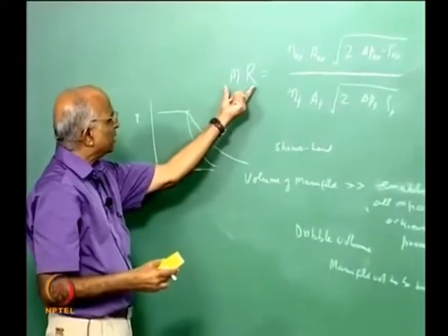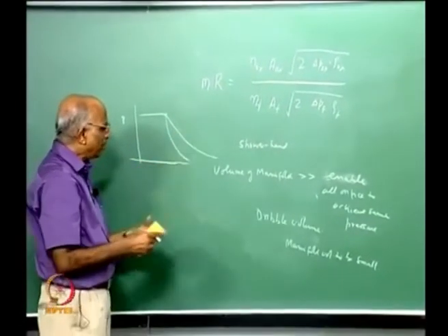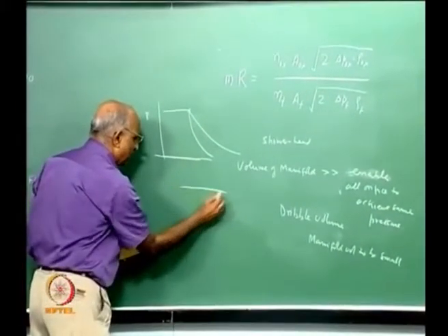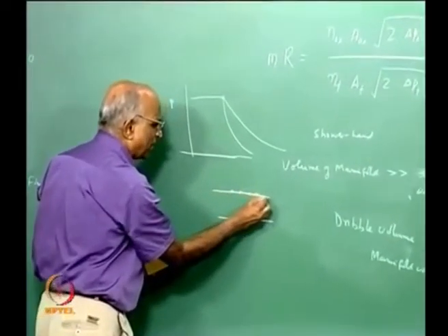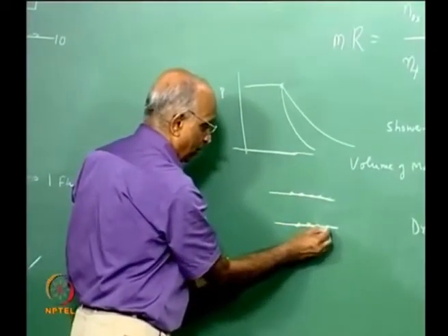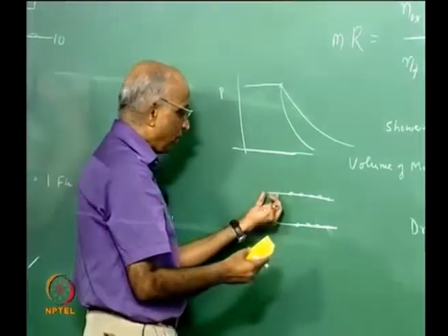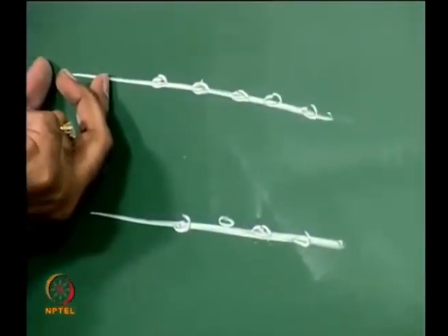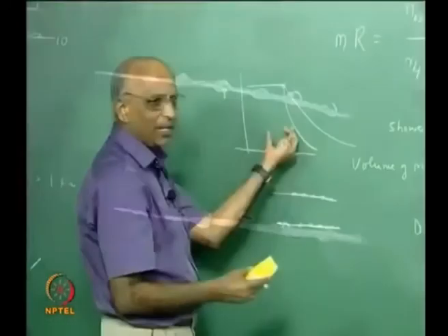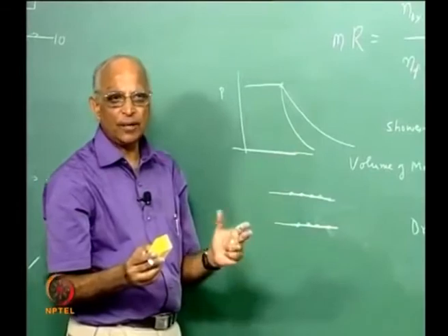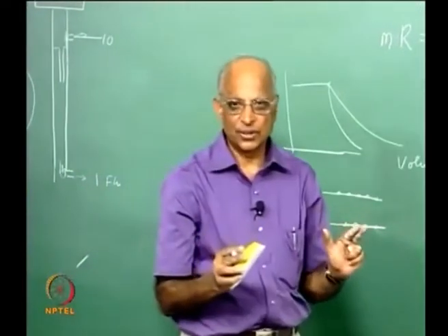But the shower head injector is something like a weak injector, because as you know, if I have a jet coming like this, it takes some definite time for it to atomize and form droplets, but you want droplets as early as possible. And though some of the earlier designs of liquid propellant rockets used shower head injectors, at the present point in time we never use the shower head injector.